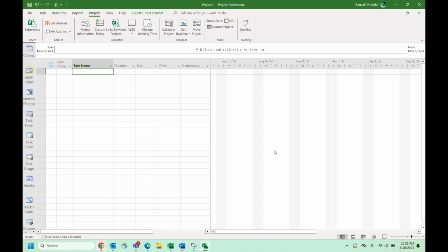Again, it is very critical that before you start your project, you declare auto schedule so that the computer will help us. Unless you are an expert who has mastered MS Project, allowing you to move around some of those activities is well and good, but if it is your first time, I'd advise you to set it to auto schedule.